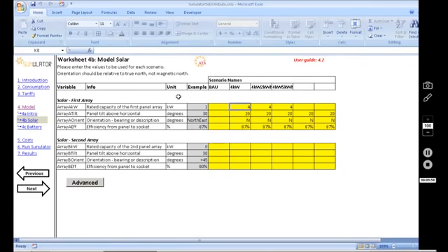The next row is the panel tilt. So that's the degrees above horizontal. So if it's a very flat roof, then that might be a 5 or 10 degree tilt. Normally you'd want the panels to be on at least 10 degrees so that they get washed fairly well by rainfall. If it's more of a traditional kind of peak roof, that might be 20 to 30 degrees. Yeah, and you could have roofs tilted more than that, or of course you could have panels on a tilt frame that tilts them up higher.